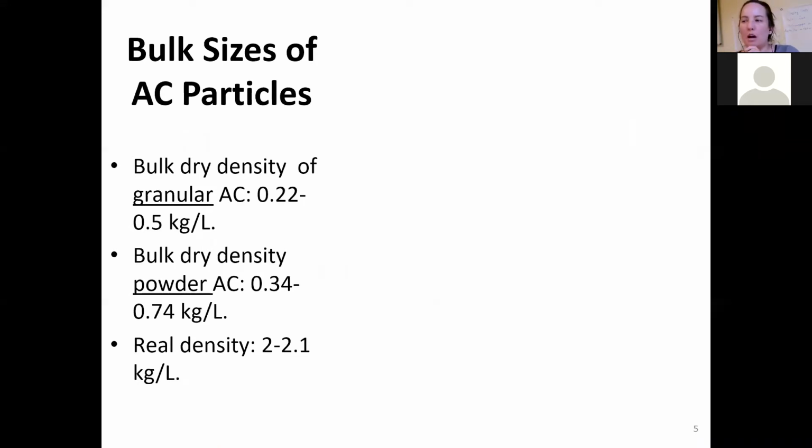Okay, when we're talking about activated carbon particles, one thing we'll need when we start doing calculations and designing these kind of filters is how much material goes into the filter. And since these are highly porous materials, it's not just the density of the carbon, but it's kind of the effective density of the material, how much carbon is actually located in 1 cubic centimeter. And since it's so porous, it's not that much, and it depends a bit.